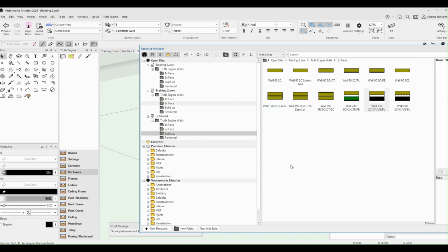So some of the things I'll mention: all of these external brickwork walls, so your T-course face, that face always by default drops down -2 courses down to the footing on every wall. But for walls like this one here, the 2 course / plaster, that 2 course face goes down to the footing, but we don't want the plaster to go down the footing, so that stops at 0.